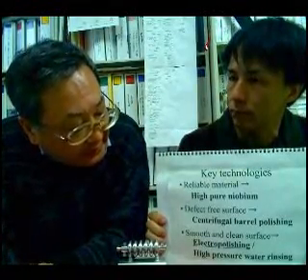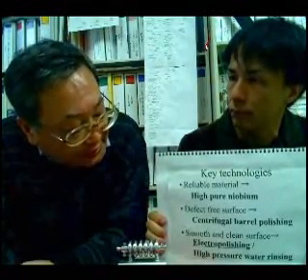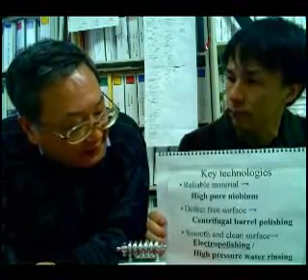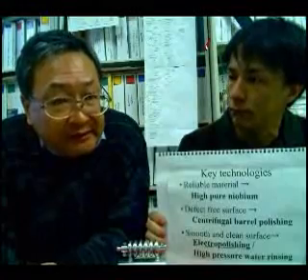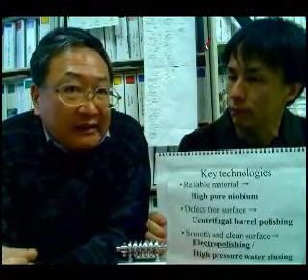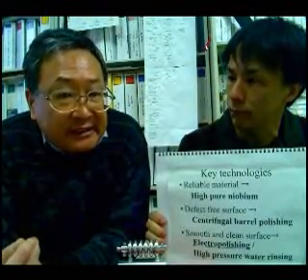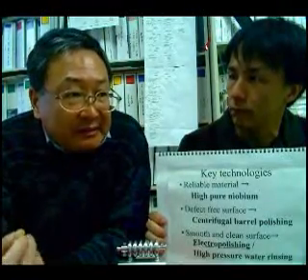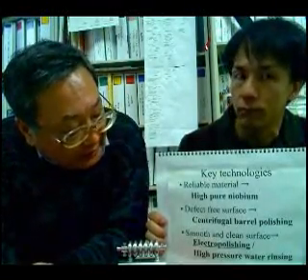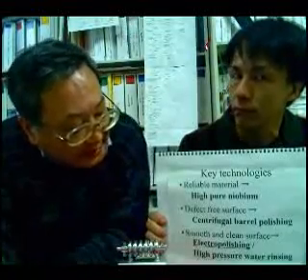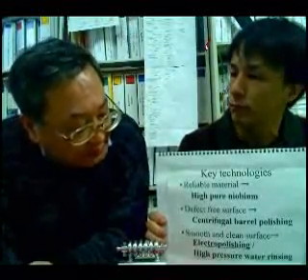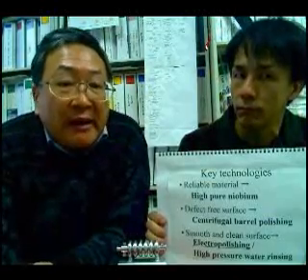And the next one, the cavity should be defect free. If the cavity has a defect, the cavity gets heated, and then finally the cavity quenches. So for this technology, we have to use mechanical grinding. Currently, we developed centrifugal barrel polishing.